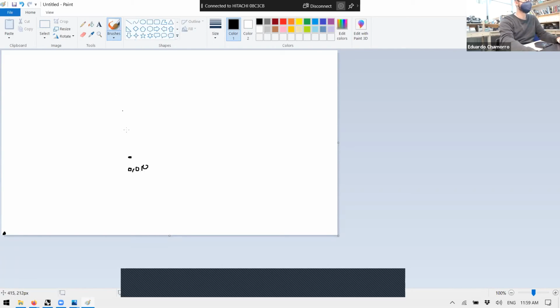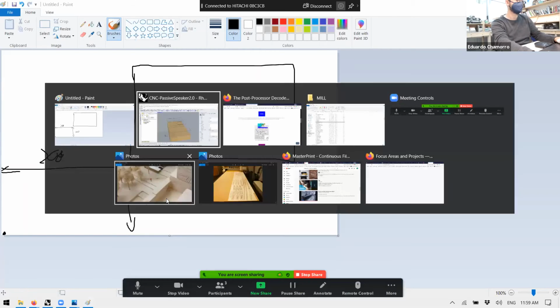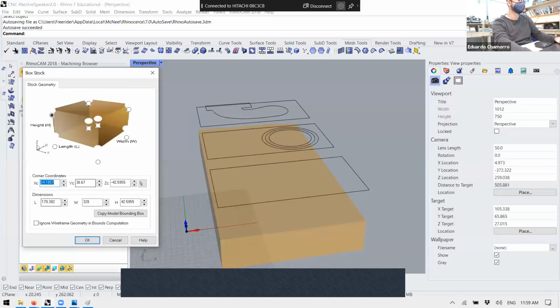It's easy. There are other ways of working. Instead of stating that, what you do is you locate your material on the machine and you measure this distance. That, of course, is a little bit annoying. You need to be really careful. You need to take a ruler and be as accurate as possible. And you can state that this is 200, for example, or 200, 100. Instead of using relative coordinates, make your own set of coordinates. You can set up always to use absolute. And you can set up also this here.